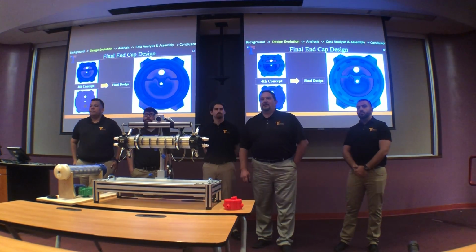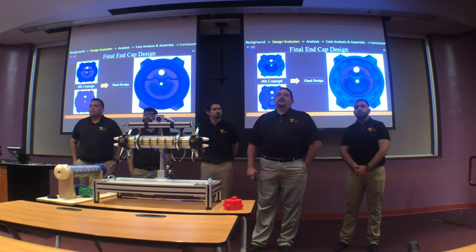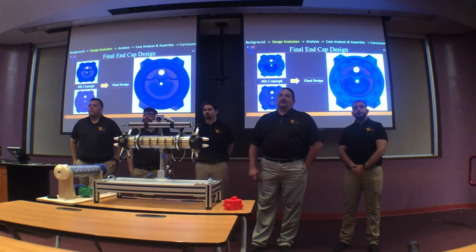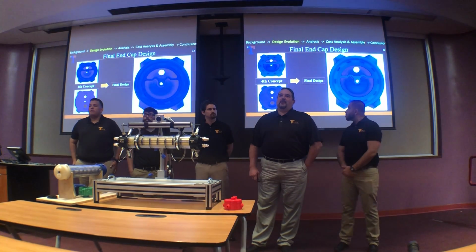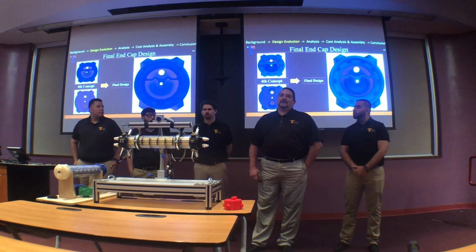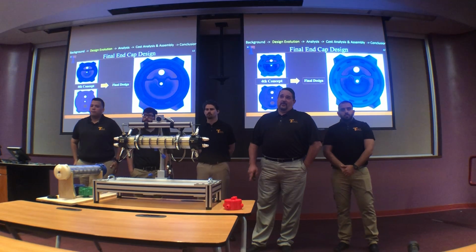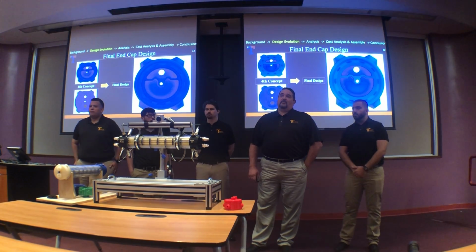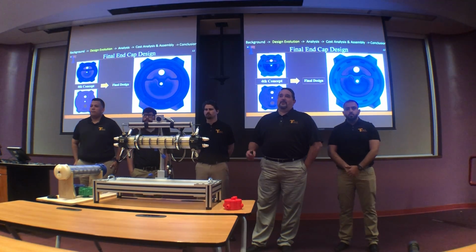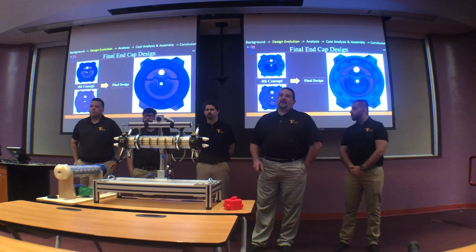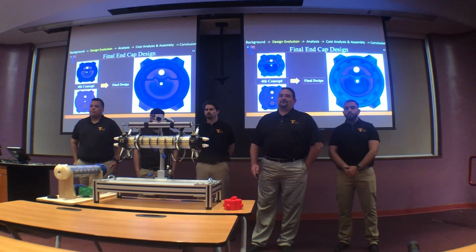I want to kind of explain a little bit about what's going on in the end cap here. So the top chamber is where the hot will come into the end cap, and the larger chamber below is where the redirect or change in direction will take place in the end cap for the hot fluid. And then the outer holes is where the inlet or outlet, depending on how you want to look at it, cold fluid flows through into another chamber in the back side, but within the cap, and from that chamber it flows out into our quick connect fittings.